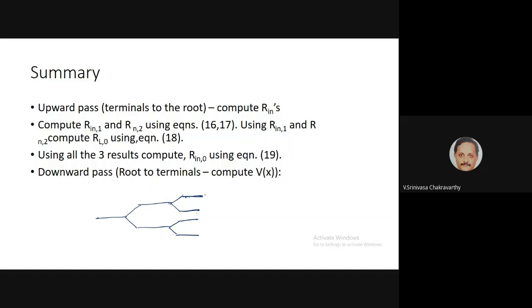so then you find the input resistance of this cable with the arbitrary loading, and this cable with arbitrary loading. Then these two come in parallel, so apply the parallel formula and find the loading resistance of the main cable. You can easily see that this can be done recursively to find the input resistance of an arbitrary sized tree. Once you get Rn for the entire tree, you apply I inject, or I naught, and you get V naught. Once you have V naught here, you know the RL here, so apply the voltage formula for the main cable with arbitrary loading. Then you get the voltage for the main cable.